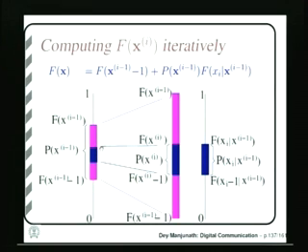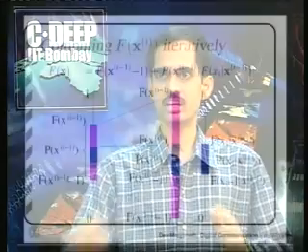Now, say these 2 points we express as binary numbers. The code word will be somewhere in between. If these 2 points have binary expressions common for a few bits, say the first 7 bits are common in both these numbers, then any number in between will also have the same 7 bits.